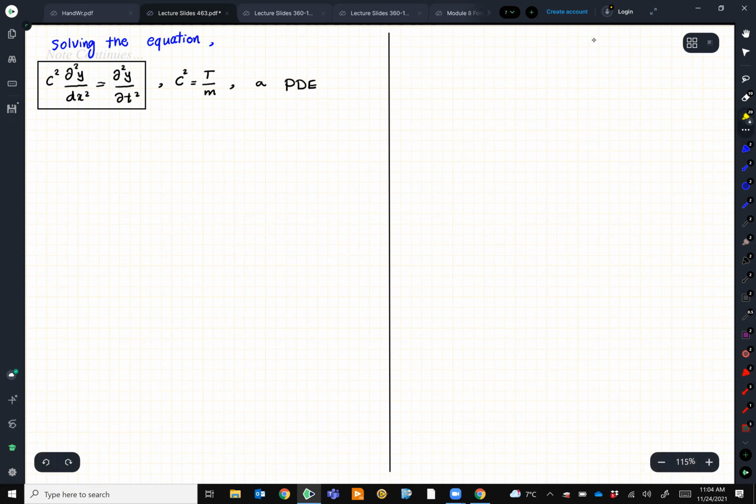So we realize that this is a PDE and not an ODE. This is a partial differential equation. All right. And there are some headaches solving this equation, but we will try to solve it with the same method that we had before. So we started by saying that maybe y of x and t, because remember now the solution is a function of displacement x and time t, we decided to go with Y(x) cosine omega t as just a guess to see how it works.